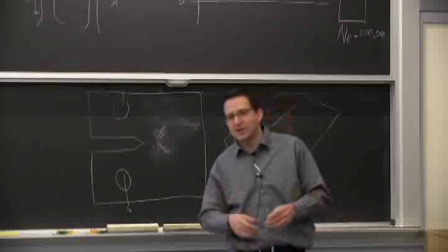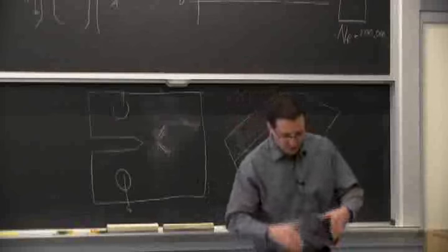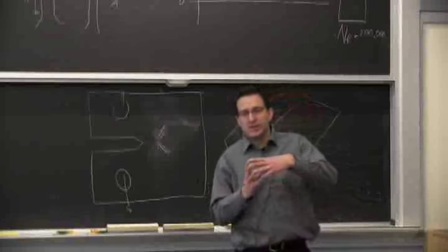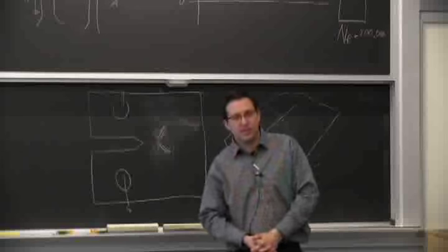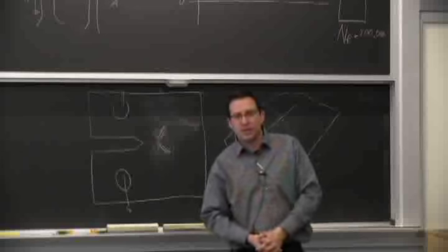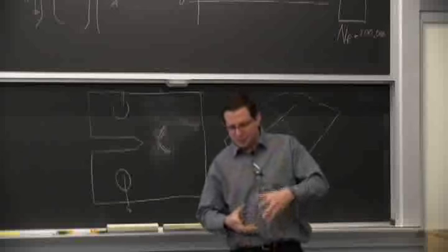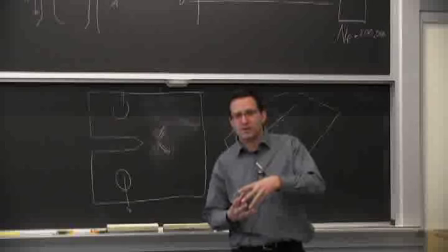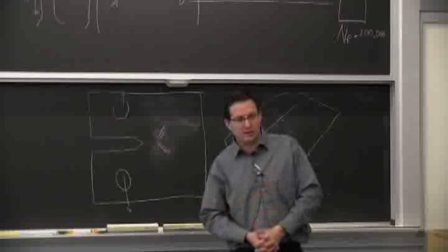We thought it was a good thing, but now we have a lower fatigue strain. Well, we know now that the bigger the plastic zone, the more resistant the tip will be to deforming back and forth. That's really the way to think about it. You'll need more K to move this chunky plastic zone to get it to smear and move any further.